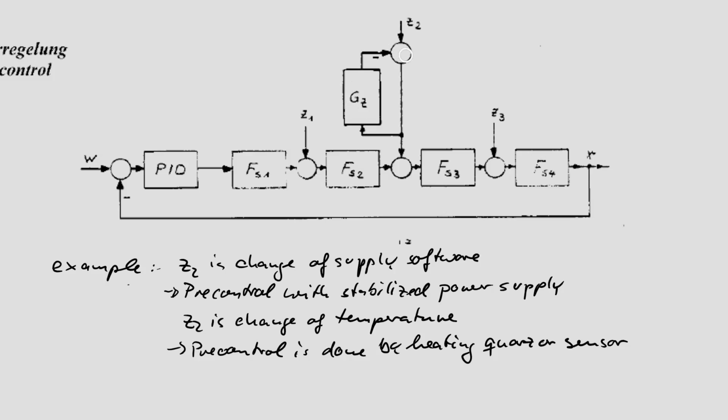Then imagine you want to prevent this torque from your speed control loop. It means you need here a second motor. Then the second motor has a problem, and the first motor, unloaded, is then working very properly, but this is not a very good help for the user because the situation now is transferred to the second motor. So sometimes the idea of pre-control doesn't work.